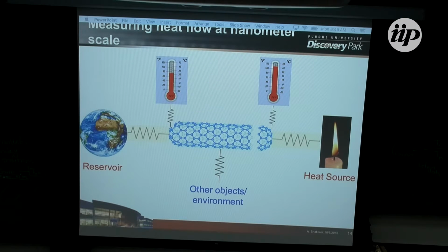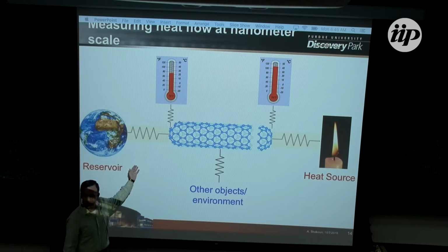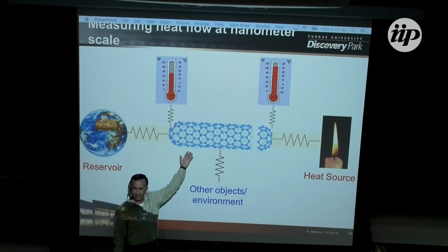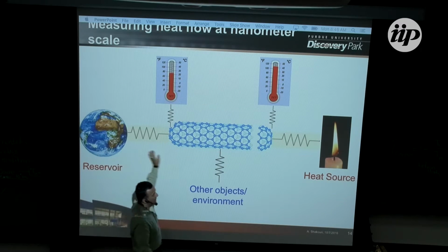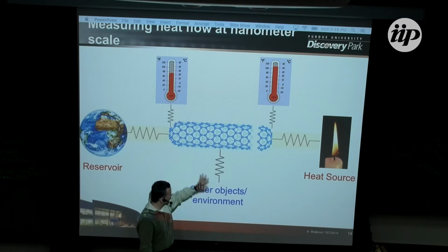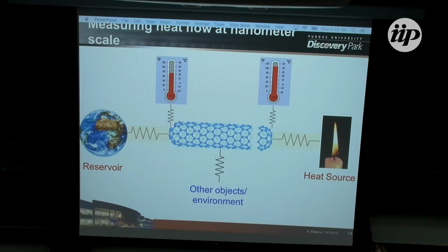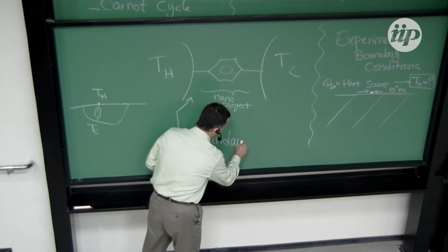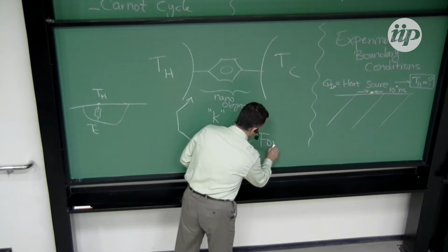So how do you do a heat conduction measurement? This is the type of measurement I told you does not excite the experimentalists as much, but still. How we do it today, we put in a reservoir, a heat source, we mimic them well. Again, it's not the real world, but we measure a heat flux and a temperature difference, we connect it. What is interesting is that the best way to describe this object or heat transport, which comes from analogy with electrical transport, is the Landauer formalism.